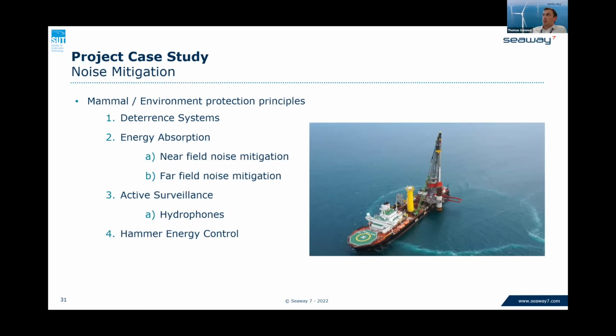So that's pretty much the installation of a monopile. For jackets, which are installed via piles, it's a similar process where you install pin piles and then a jacket's installed over. Or what you see again nowadays is jackets with suction caissons, and they use a different working principle where they create a vacuum between inside the caisson and the seabed and suck itself down. But the principle there is similar in that the heavy lift vessel is lifting that foundation and placing it over the final position.